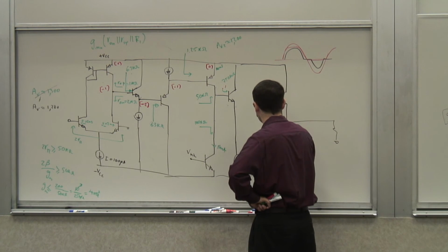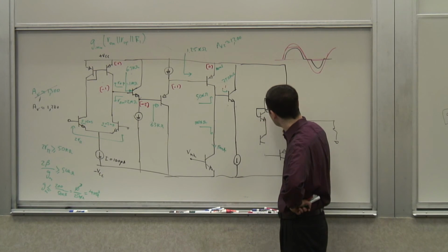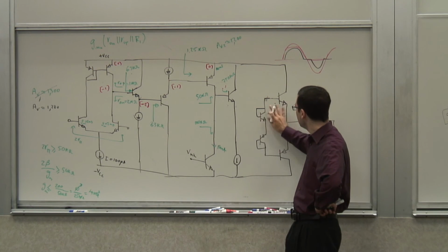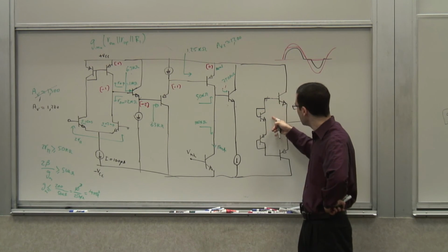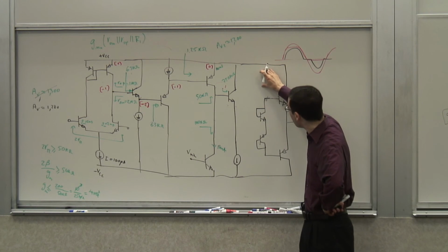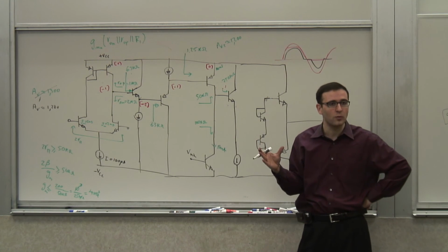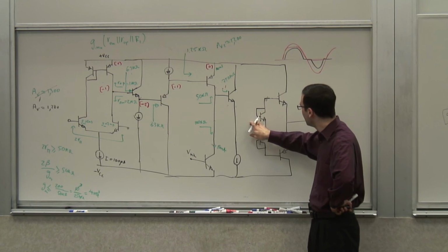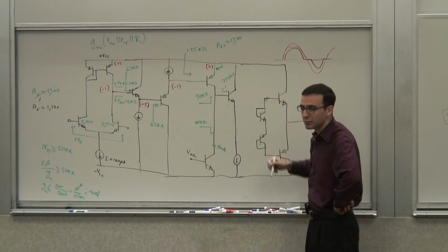So these are diode-connected transistors, and if you want to match these well, you probably want to take an NPN in diode-connected like that, and take a PNP in diode-connected like that. Now, the thing is that if you do this, you have a VBE to match this VBE and a VBE to match this VBE. So in that case, if you want to maintain the same VBE across both of them, you have to maintain the same current level as the output, right? Which is too high, because this is the output driver. You don't want to throw half of that current just burning inside a branch. So what would you do to maintain the same voltage level while driving a much lower current into this branch than that branch?